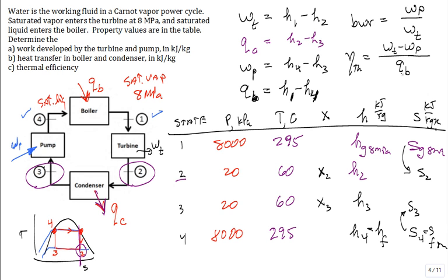True? Somebody said, Professor, you just studied the Carnot vapor power cycle. I learned that the Carnot vapor power cycle has a thermal efficiency that's 1 minus the low temperature over the high temperature. So I would take this high temperature, add 273, because I don't want to make a mistake and put in degrees C for TH. I want to put in Kelvin for TH. And so that's TH. All right. And then I go and get TC or T low. That's 60 plus 273. And I put that right there.